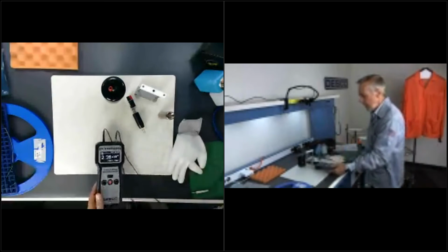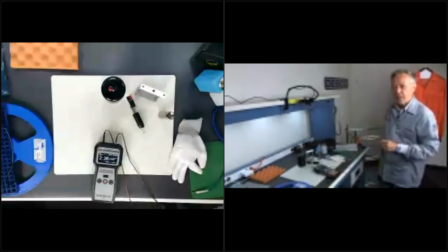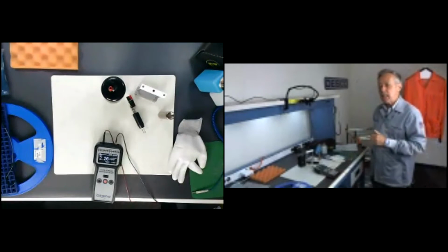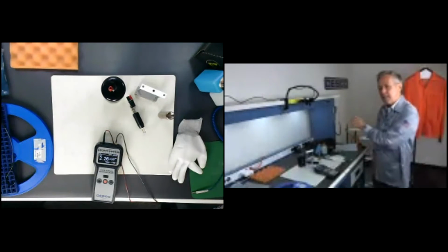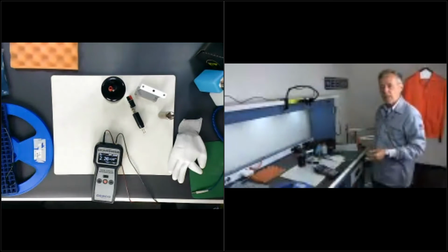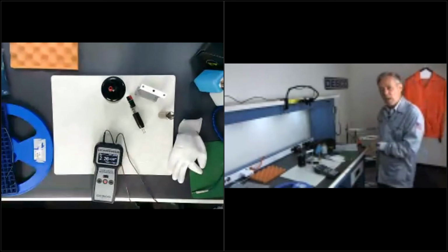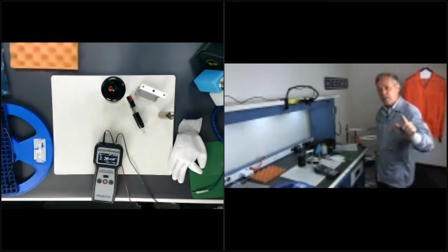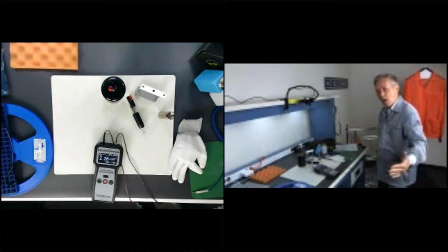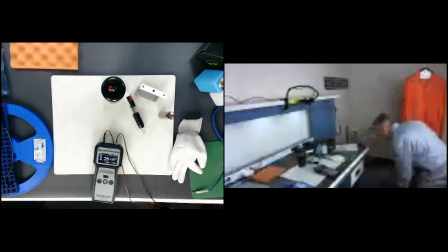Now, let me make a point as to why the 36 inches. The reason for that is because that was originally set up for when you were checking ESD tiles. So what we want to make sure is that each tile is connected together properly via the conductive ground plane, or what is typically a conductive adhesive. In the case of the snap together floor, that also proves that all the tiles are touching when they're snapped together. So that's why you need to measure at a longer distance than you do a work surface.